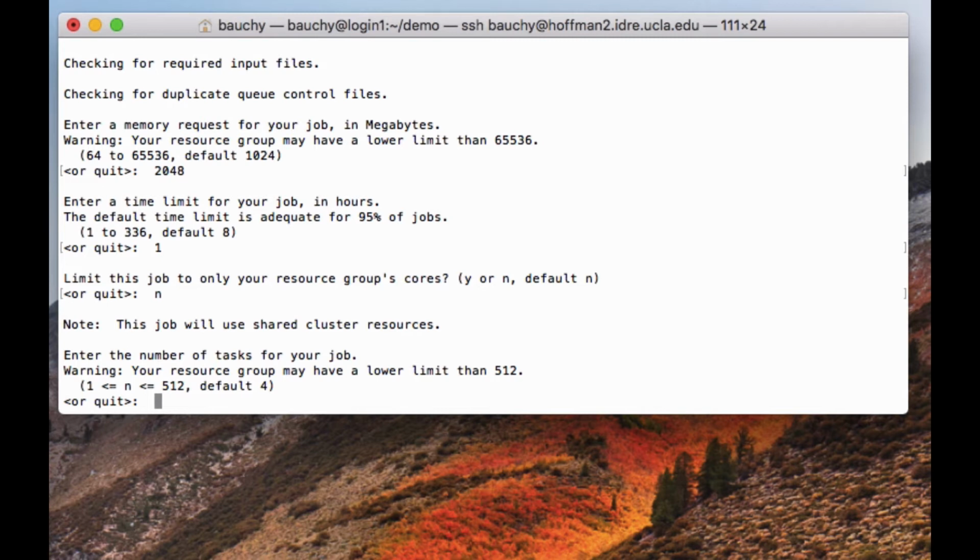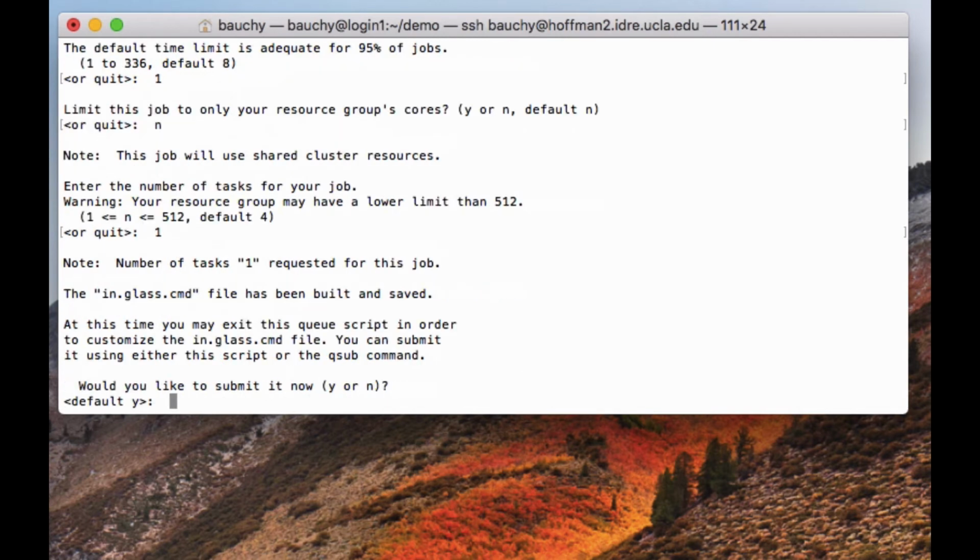On the other hand, if you ask for too many cores, at some point the efficiency of your simulation will decrease, because you will have to wait for the cores to communicate with each other, so you will lose some computational efficiency. So usually you will want to use either 8 or 16, which are typically good numbers, so that your simulation will be fast enough but remain efficient, and you won't have to wait too long in the queuing system. Typically 8 is a very efficient number. Here we will ask for only one processor so that your simulation can start as soon as possible.